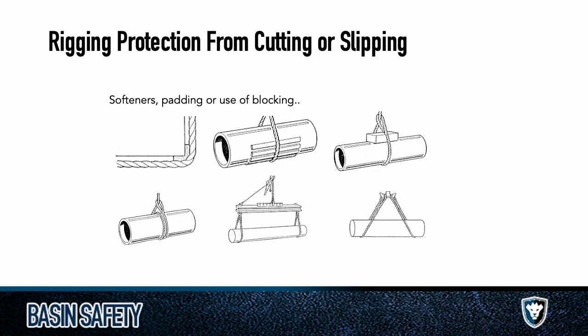So to prevent slipping, you may need to add different padding, blocks, softeners, etc., so that the rigging equipment doesn't slip. And that's something that, again, when you go through the course, you'll get a better handle on.